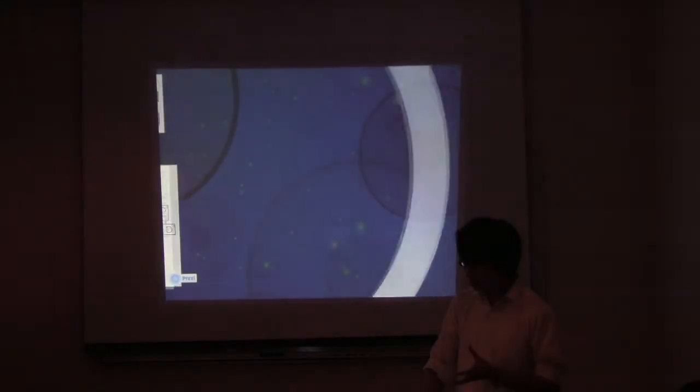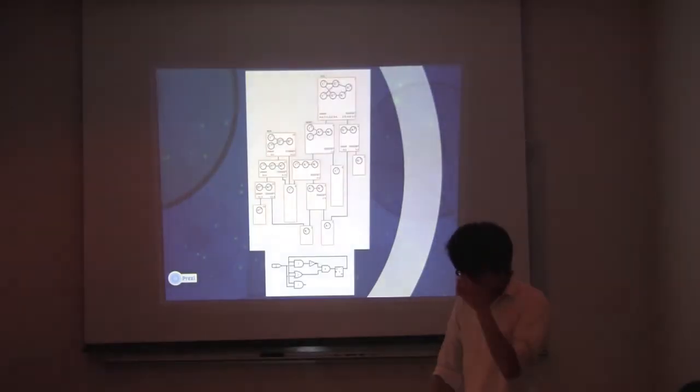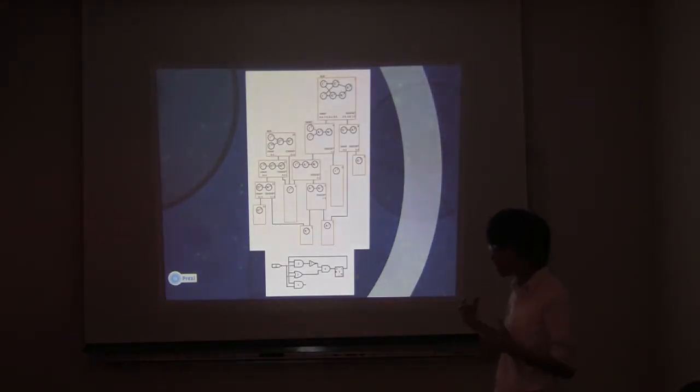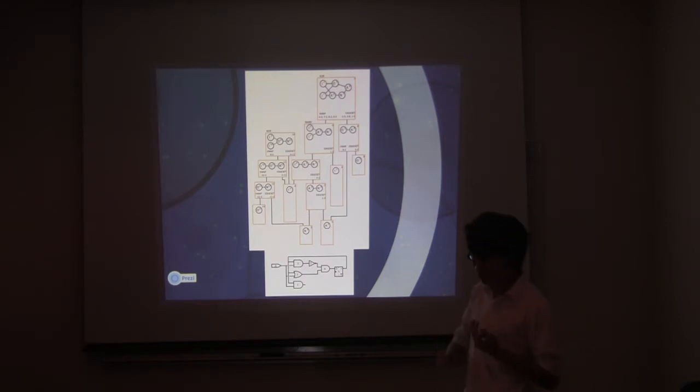So once the decomposition tree has been built, when we're performing a match with a reference circuit, we use the tree to do that. There are three states each node in the decomposition tree can be in. Initially, all the nodes are labeled unsolved. If there's a mapping that can be made, the node is marked alive, and if no mapping can be made, the node is marked dead.